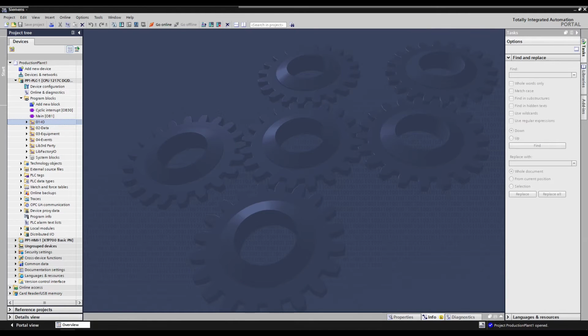As we can see on the left side, we have several numbered folders, each folder representing a separate layer in the control software. The I/O layer is responsible for exchanging data between the PLC I/O registers and the user-defined type instances I created for each device type.